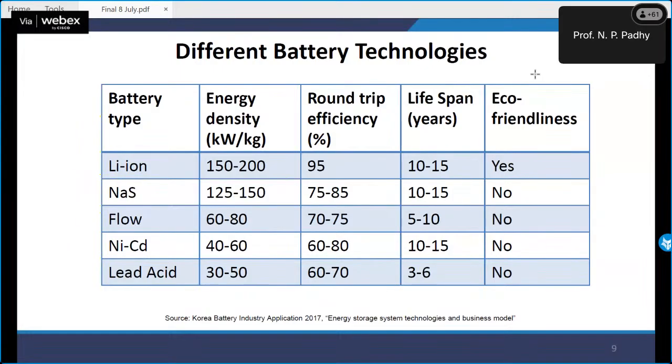So with that philosophy, it is not about the energy efficiency, but it is about the financial benefit or meeting the peak hours load requirement. We always take the water back during off-peak hours. So whenever we have excess energy available during off-peak hours, that excess energy can be used to pump the water back to the dam, and that can be generated during the peak hours.